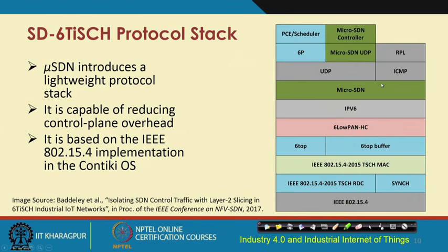have the concepts of the micro SDN, and this micro SDN basically introduces a lightweight protocol stack. It is a lightweight protocol stack that is capable of reducing the control plane overhead, and it is based on the IEEE 802.15.4 implementation in the Contiki operating system, which is for simulation of sensor networks. Contiki is widely used. So, this basically runs on top of the Contiki operating system.